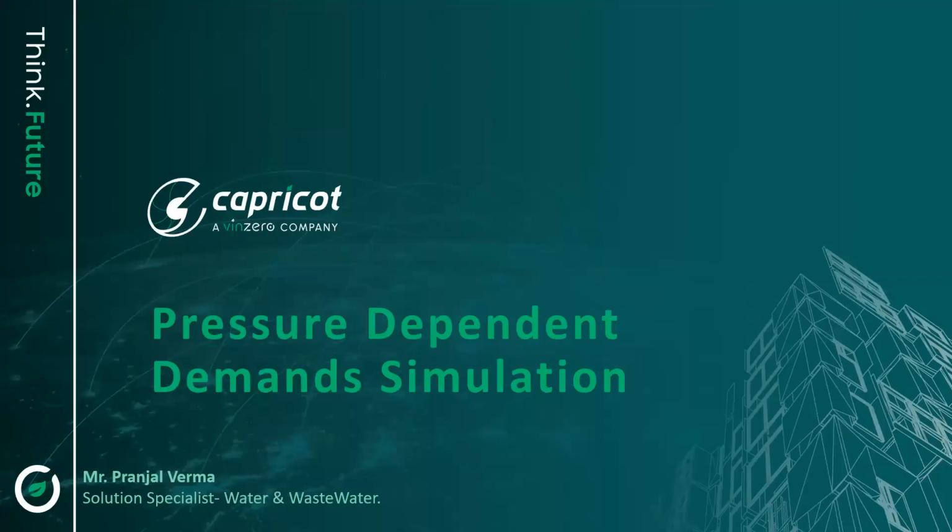Hello everyone. Today I, Sanjay Verma, solution specialist in water and wastewater, talking from Capricorn Technology, bring you a weekly insight on how we are going to simulate the situation where a change in pressure affects the quantity of water used with the help of pressure dependent demand in WaterGEMS.